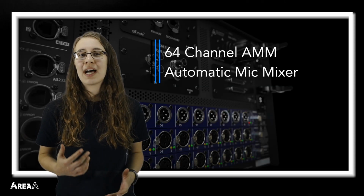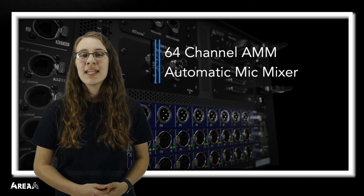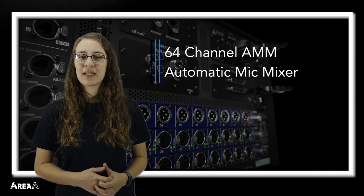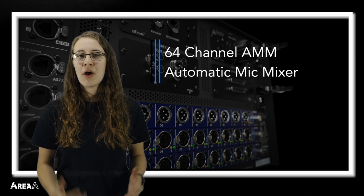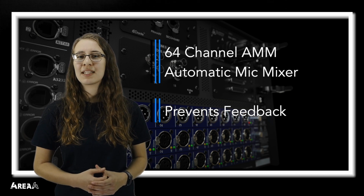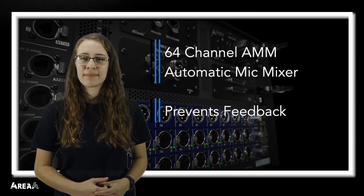The 4U4 has a built-in 64-channel automatic microphone mixer, or AMM for short. The AMM takes multiple inputs of speech and automatically turns up a channel when a speaker is talking, and turns it down when they stop. This is perfect for interactive congregational discussions and situations where multiple people need to be talking at the same time, as it prevents feedback normally associated with having lots of open microphones.